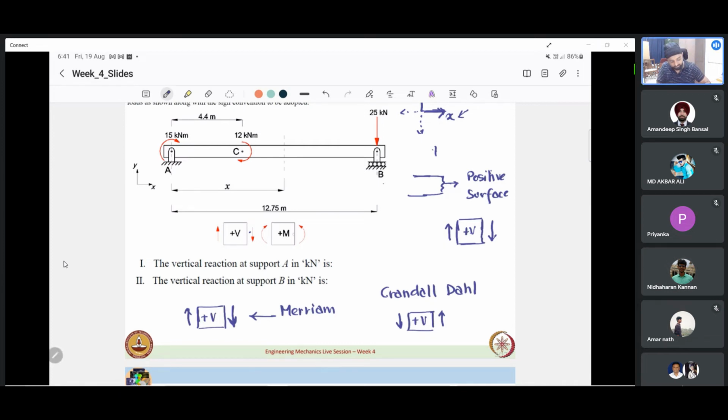I think I understand what you mean. I'll complete my explanation and then if there are any remaining doubts, please ask. So the question is, generally, if we consider an XYZ coordinate system, the Z will point outward because of the right hand rule. So any moment that is taken anti-clockwise is considered to be positive because its axis will align with our moment's axis. That is why anti-clockwise moments are taken to be positive, clockwise moments are taken to be negative.